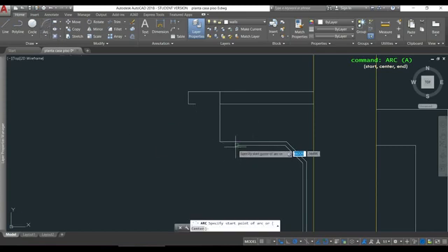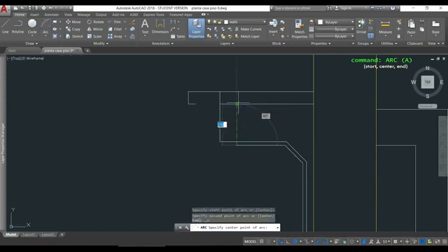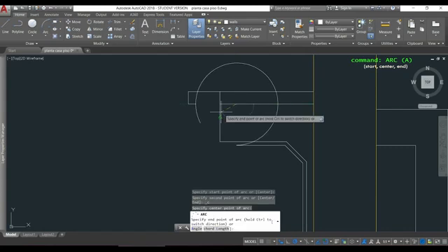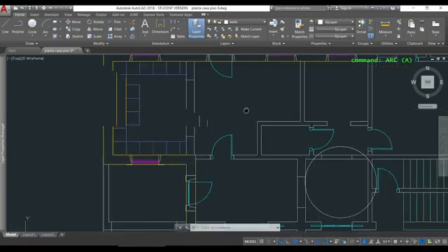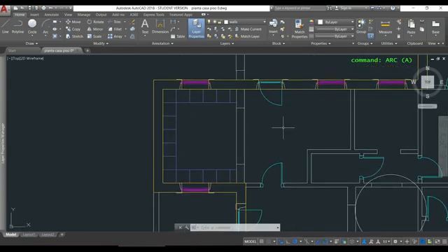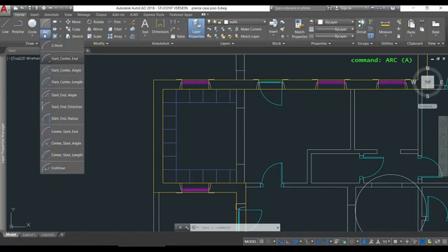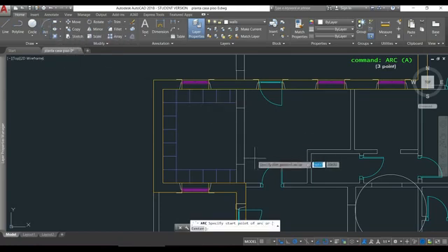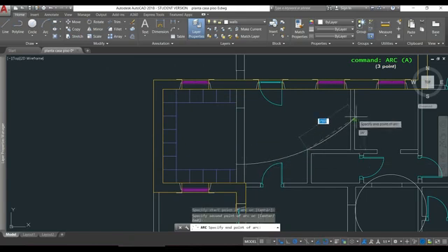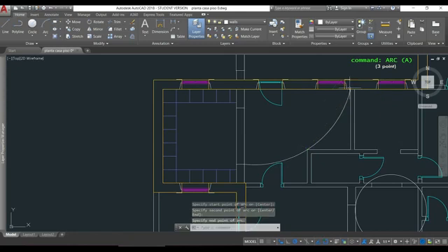And with this, I mean that if you want to draw starting with this point, then click there for the center, you will not be able to draw it as before. Now I want to draw an arc using these 3 points. I choose the option 3 point, then easily just click in the first point, in the second and the third. This maybe is the easiest way.